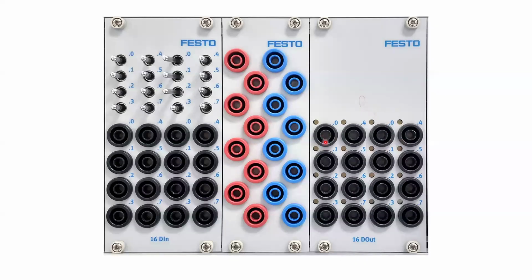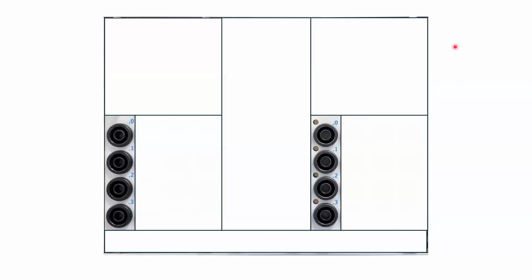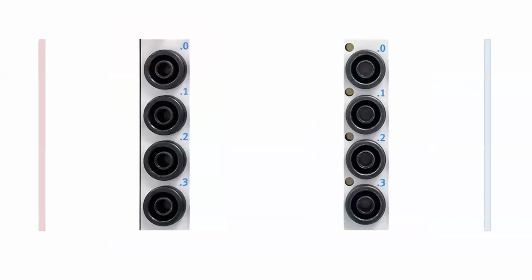And over here are the outputs. If the output is energized, it's going to have 24 volts appearing on that with a reference to the power supply, ground, or the negative rail, which is connected to ground anyways, quite often, if not all the time. And you're going to have the pilot light come on. And those are assignable. Alright, so quickly just concentrate on that part. Concentrate on a couple of those, just one row to make things easier. And magnify it. See how nice?